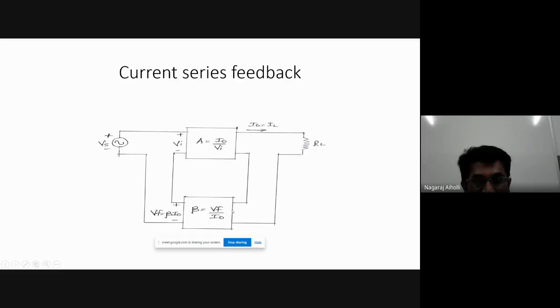Now, beta is the feedback factor. Its output is Vf, that is the voltage, and the input is the current I naught. Vf by I naught is the feedback factor beta, or Vf is equal to beta into I naught. Okay, so this is the current series feedback.